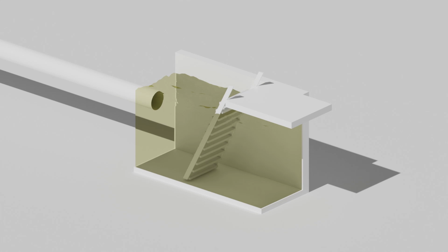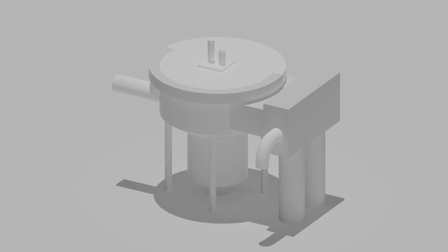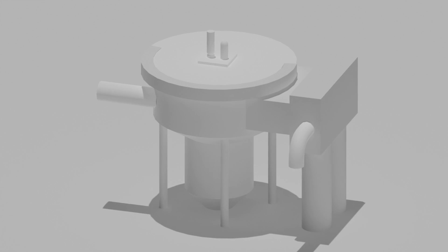The first step for our wastewater, known as influent, is to go through the bar rack. The bar rack consists of screens designed to filter out larger masses in the sewage to prevent damage of equipment. Once these objects are removed, the influent travels to the grit remover.